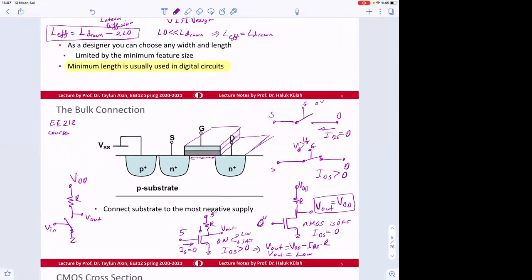With the same concept, maybe we can make one switch or another switch. If we put 2 transistors like this, and this is V out, and this is VDD, and these are the A input and B input, then what we obtain here is A dot B bar, or NAND gates.